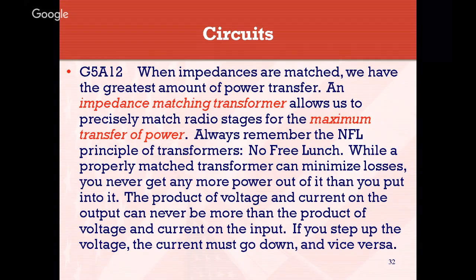So you don't want an impedance mismatch. This is what happens on your antennas. Your radio output is actually looking for a nominal impedance of 50 ohms going out to the antenna. And if your antenna is mistuned, the resulting mismatch in the circuit will cause a higher impedance that your transmitter is not going to like.